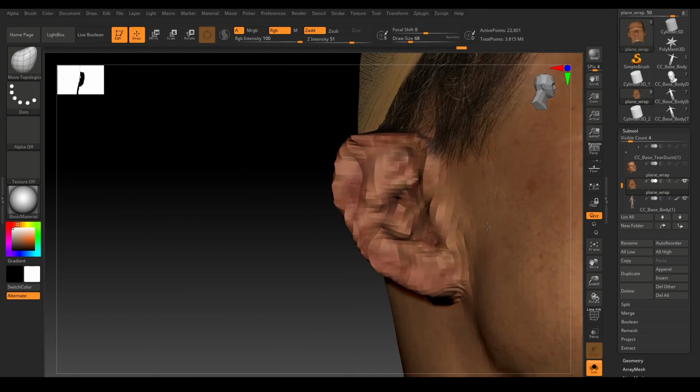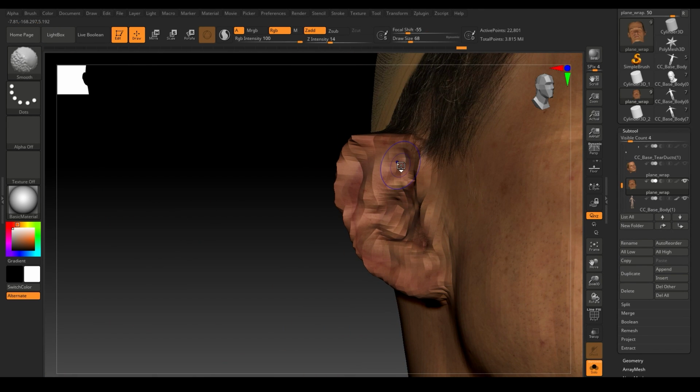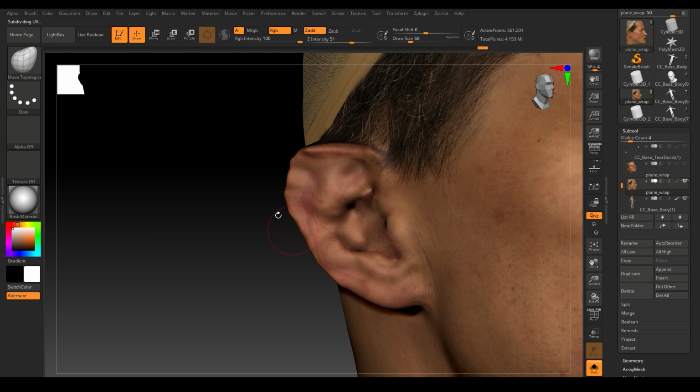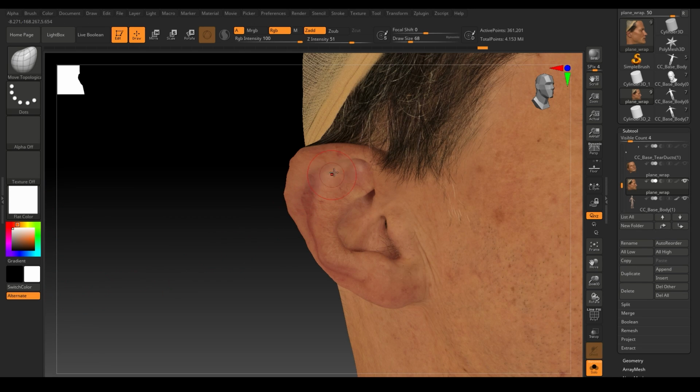Okay, another tip for this also is to subdivide. So I did 2 subdivisions on this. Just means that you can get a smoother projection. Okay, so something to notice here is that the color information needs to match. So if we jump into flat view mode, we can see there's horrible distortion here of the texture map, right?